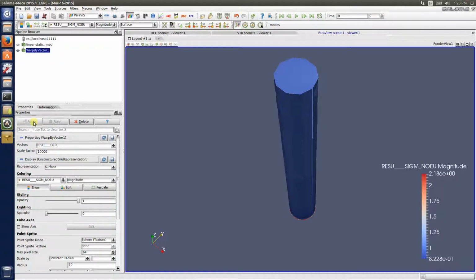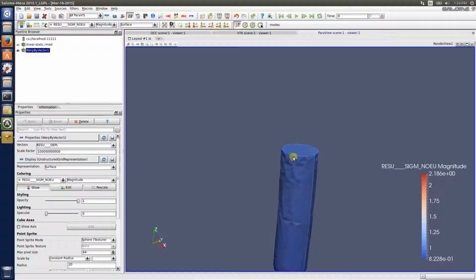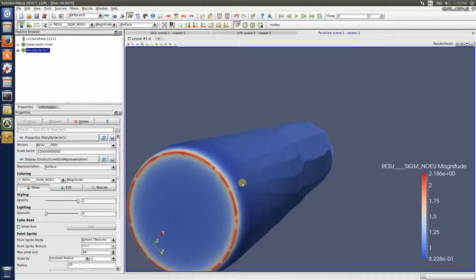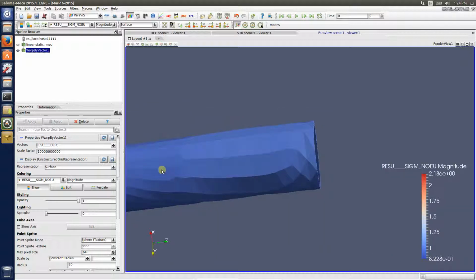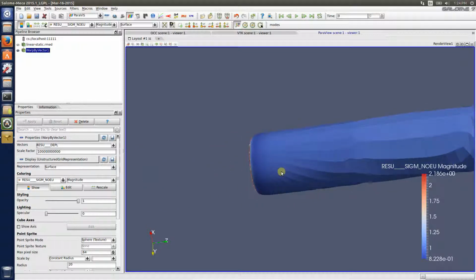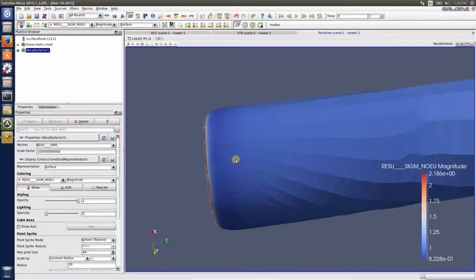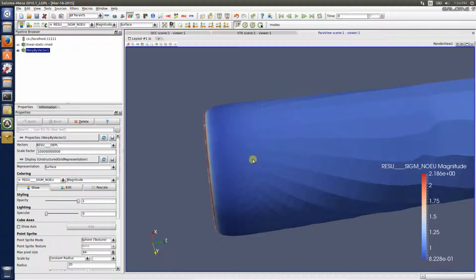But what you can do is head on up, increase this. I may have gone too far. Sort of did. But what you'll notice is, take a look at the bottom. If you look at this, essentially you can see, and I might be able to see it better by looking at a profile view of it. Here we go. You can tell that essentially the table has held the original size of the ring fixed, and as you push it down, it's as if you took that table shut and created a stress around the ring in the edge. So you can see how the boundary condition you put can really affect your stresses.